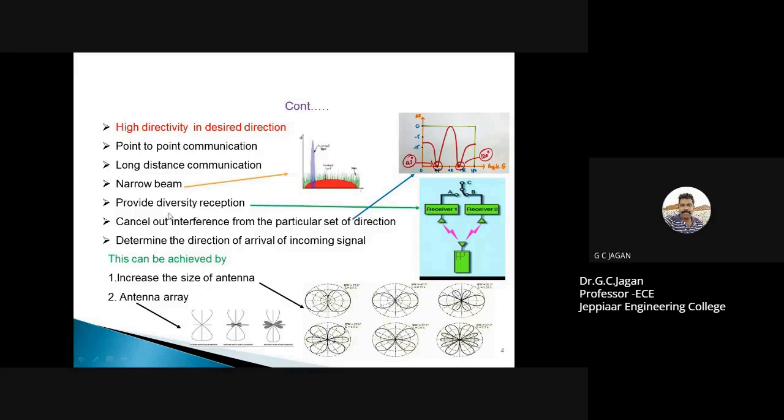Adaptive equalization is nothing but using an adaptive filter bank. Now you know the function of a filter: it removes unwanted noise signal with the desired cutoff frequency. A normal filter's cutoff frequency is static. But in wireless communication, we don't know the behavior of the communication channel, so to handle the noise we normally include an adaptive filter.